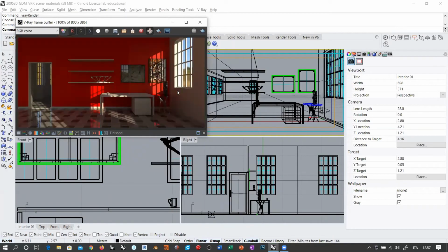So personally, before starting to tweak V-Ray settings in a very specific way, what I would do is eventually tend to decrease the saturation in order to avoid excessive coloring of the primary bounces, which are the most effective bounces that you get in terms of illumination inside your environment.